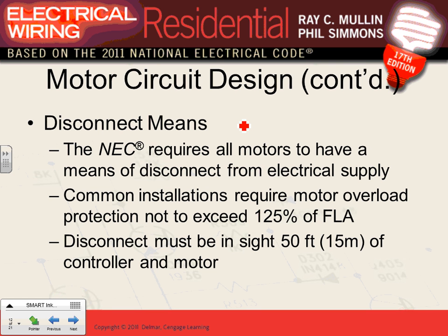Safety. The one who locks it, tags it, or works on it could be an electrician, a mechanical contractor, or a control person. So the disconnect is for a lot of other disciplines. We'll talk about the disconnects. Typically, we size the disconnect at 115 percent of the full load current. We'll talk about these in a second.